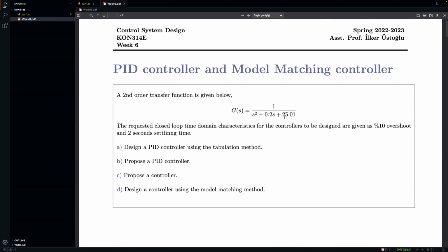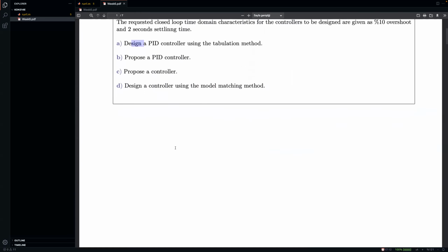So the best that we could do is to embed a bandstop filter. That would make more sense. Of course, the filter dynamics are included in the behavior of the system, so that limits us somewhat. But theoretically, we could just say, okay, this is the best controller that we came up with in C and T, but it is dangerous because it's around the j omega axis. In practical world applications, if this doesn't work, we have to opt for the one in A, which is way better performing in terms of modeling errors and stuff, but the shape is a little bit weird. So yeah, that is basically it here.